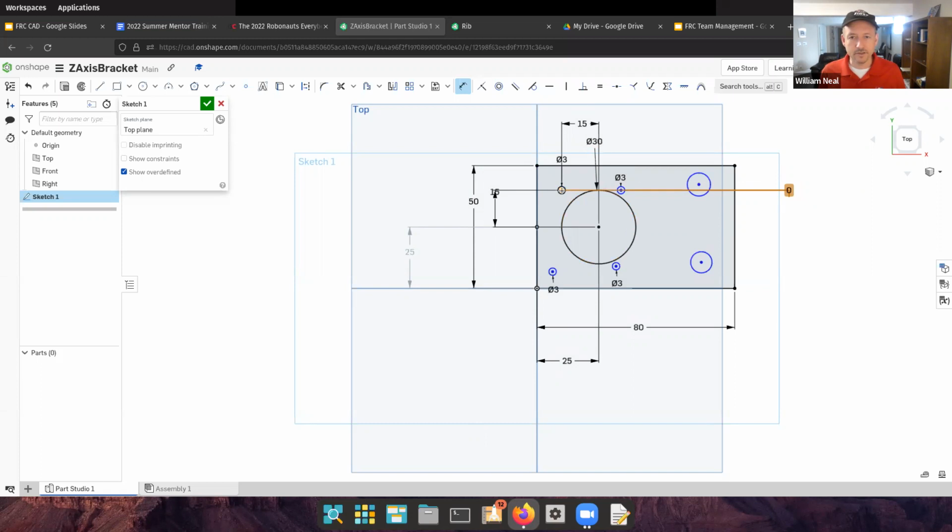And you can see here, this line length should be a little bit longer. So let me hold down shift and select these 2 points here. And the distance between those should be 30. There we are. And so on, I can continue going around my object and constraining it so that these points are centering around this hole.